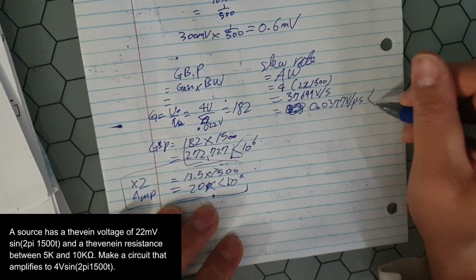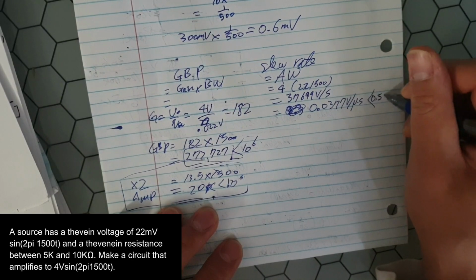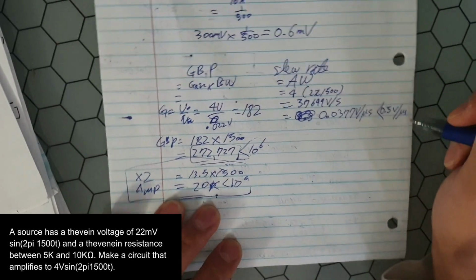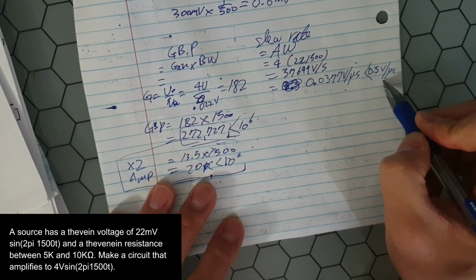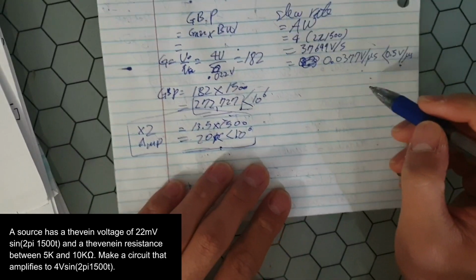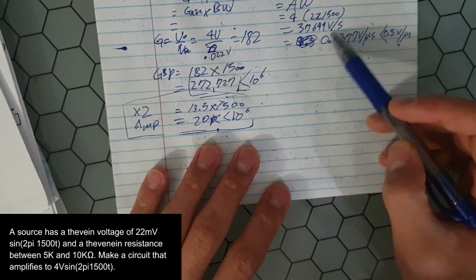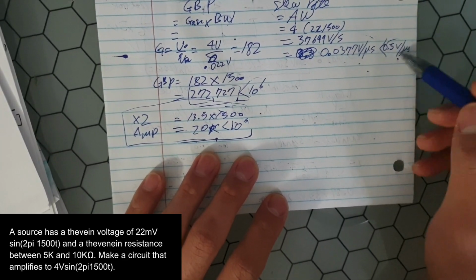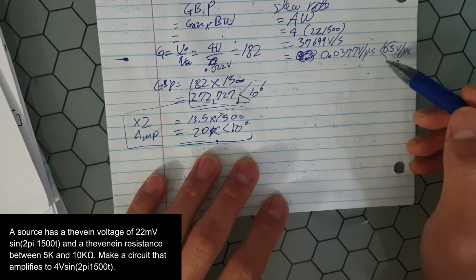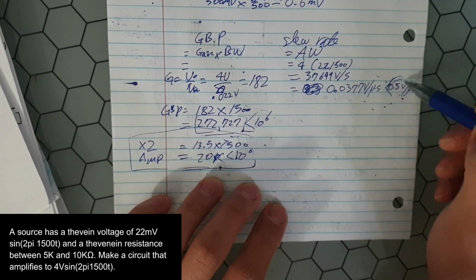A typical op-amp has about 0.5 volt per microsecond of slew rate. So since our slew rate is smaller than this, we should be able to use the op-amp we are using. And if the slew rate that we need happens to be bigger than the specification of the op-amp, we should be using a different op-amp that has better performance.